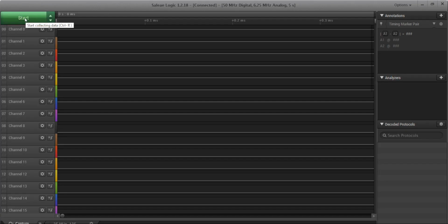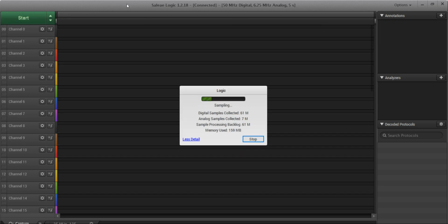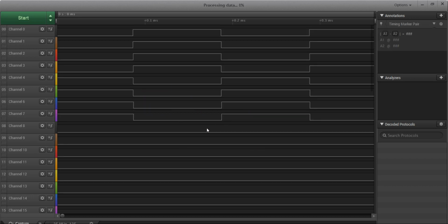Okay, so this is a logic analyzer. If I press on start, I have pressed. It is taking some time again. Yes, great. If I stop it, great. You can see here, the first four signals are showing 1 1 1 1 and the last four signals showing 0 0 0 0. In the next 100 microsecond they become 0 0 0 0 and the last become 1 1 1 1. That's great. The system is working.